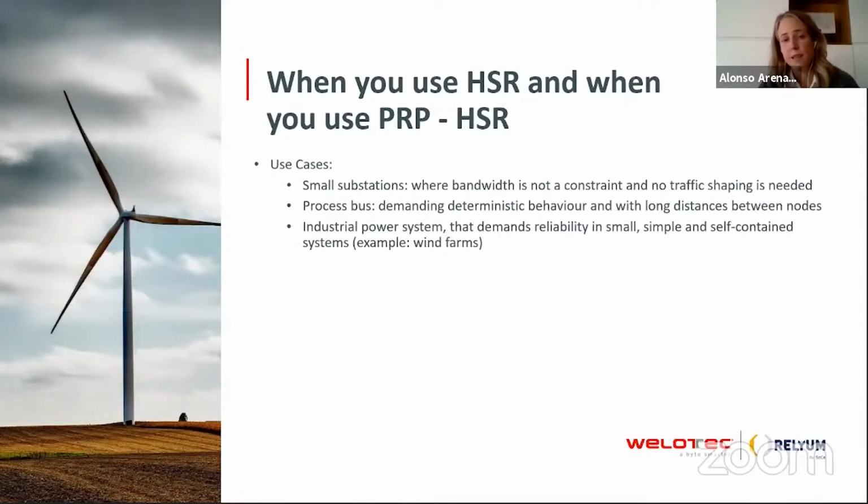Also process bus in a large substation. I explained it before. The ring topology implies some important cost savings in the cabling of the network. And also HSR is becoming more and more popular in some renewable plants like wind farms.